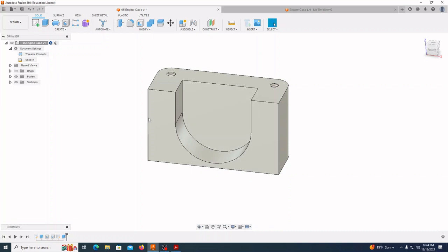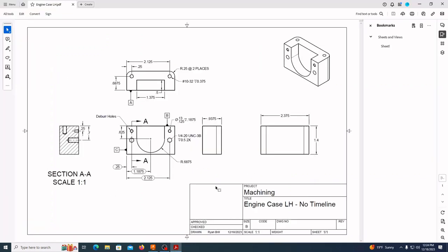The last thing that we want to do when we look at the prints on this operation is we have these top holes right here, which are 0.25 or 250 thou from the top going down there, that are also measured 1/4 inch in. And then also these threaded holes right here, which are 0.7 or 700 thou going down right there, and they are also 1/4 inch in as designated by that dimension right there as well.